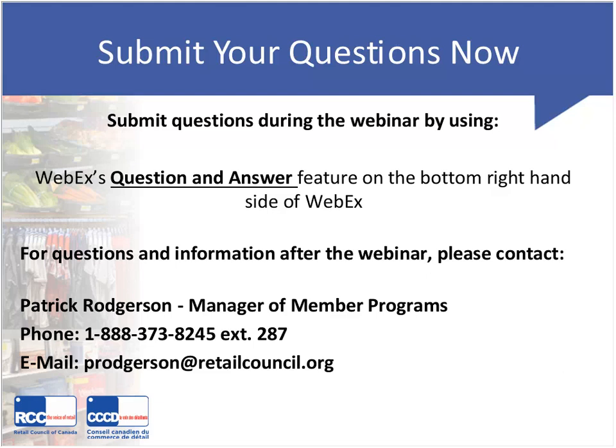Okay, Chris, I've got a tough question for you now. 2 words, heritage building. Well, again, you're dealing with a situation where you probably may not be on a barrier-free path of travel. Yep. So barrier-free path of travel, the basic minimum is you have to be less than, and I said I wasn't a millimeter guy, but it's 800 millimeters difference in grade, or basically 1 step above the exterior area.